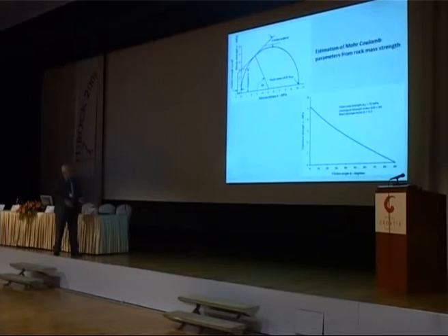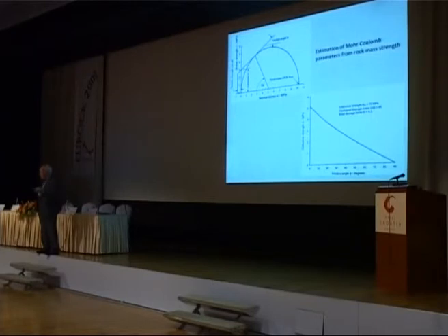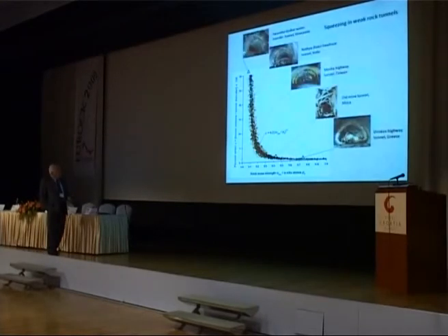And in order to utilize that in an engineering sense, if you know what the rock mass strength is, you can estimate the friction and cohesion. You have two unknowns, but you know that for many cases, the friction will be around about 30 degrees, so you can estimate the cohesive component. The mathematics can get a lot more complicated, but the fundamental approach is the same for all of these systems. And what that enables us to do is to make some useful predictions.